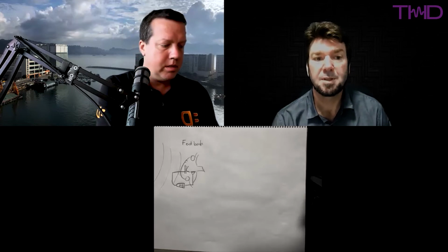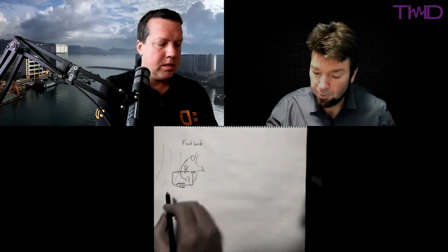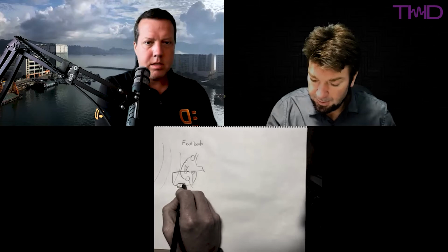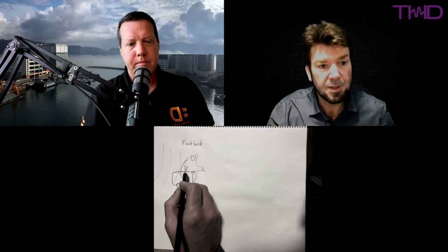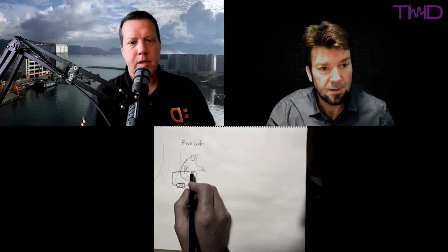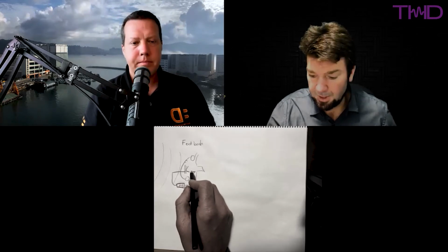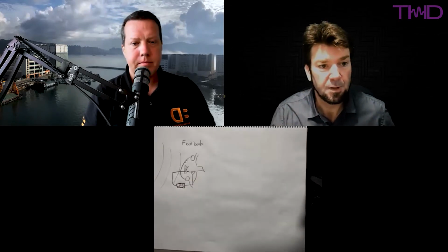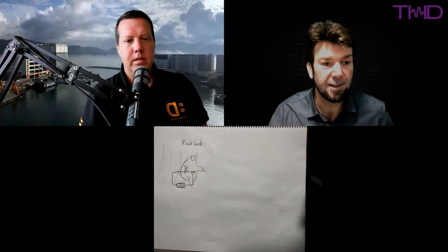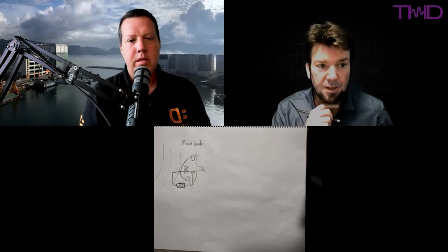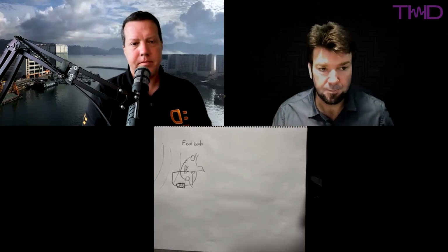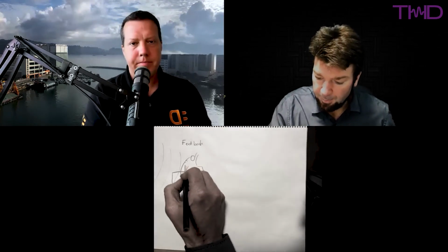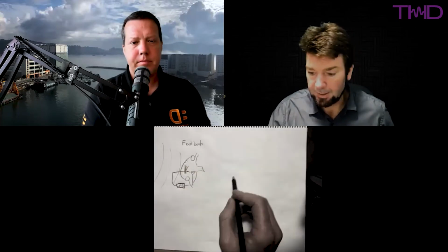Some of them potentially, but what you've done with the filter is you've arranged it so that the signal coming out of the speaker is always opposite phase to the signal coming from the microphone. So they never add together. That's your objective. And what you end up doing is reducing the sound always. Okay.